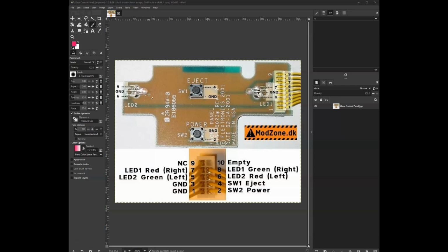But when I'd unplug those LEDs from this Xbox board, it'd boot up just fine. I wouldn't have that infinite restart. So in order to keep pretty close to the original look of the Xbox, what I did is I removed these LEDs. You can see here, I removed the old ones. I completely deleted all the wiring and used my own external.